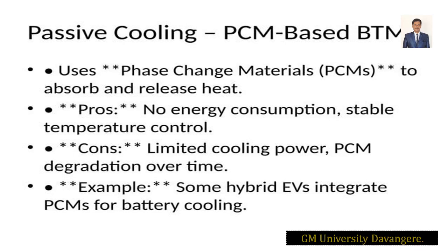Alright, next, what is passive cooling actually? Passive cooling is nothing but, as I told, no power is consumed by these kinds of cooling systems. When you talk about passive cooling, PCM materials can absorb and release heat immediately. PCM stands for phase change material. The materials are usually paraffin wax or salt hydrates that melt at a specific temperature like 35 to 42 degrees centigrade. So that's how the PCM works.